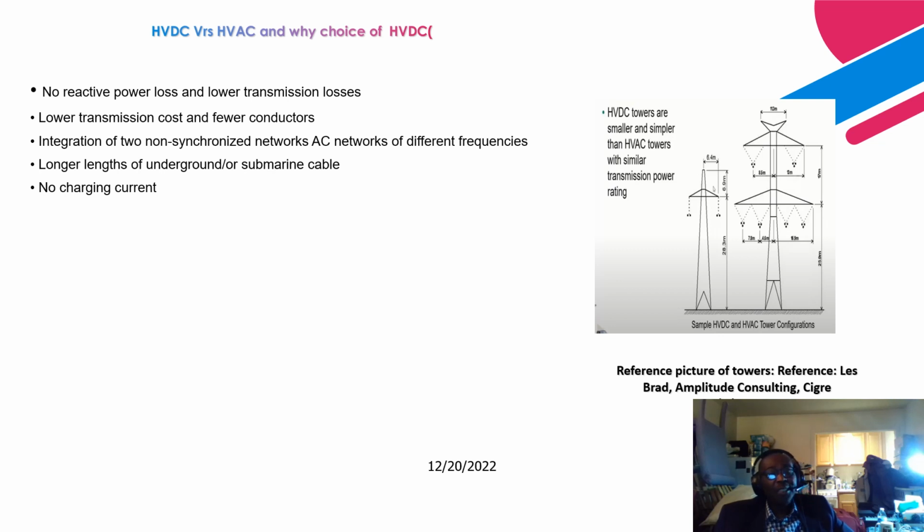And for transmission conductors, there's something they call stray capacitance. It is invisible. You have a stray capacitance that basically forms an invisible capacitance from the conductor to ground, and in AC transmission, you need to charge that stray capacitance. So that itself requires a higher amount of charging current and charging reactive power to charge that capacitance.